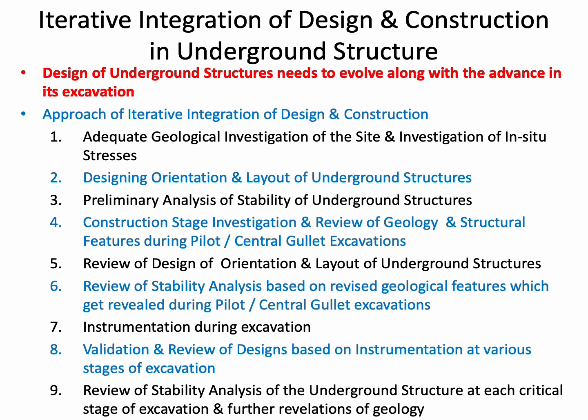Design of underground structures needs to evolve along with the advance in its excavation. The approach of iterative integration of design and construction involves adequate geological investigation of the site and investigation of in situ stresses, designing the orientation and layout of the underground structure, and a preliminary analysis of the stability of underground structures to be done beforehand.